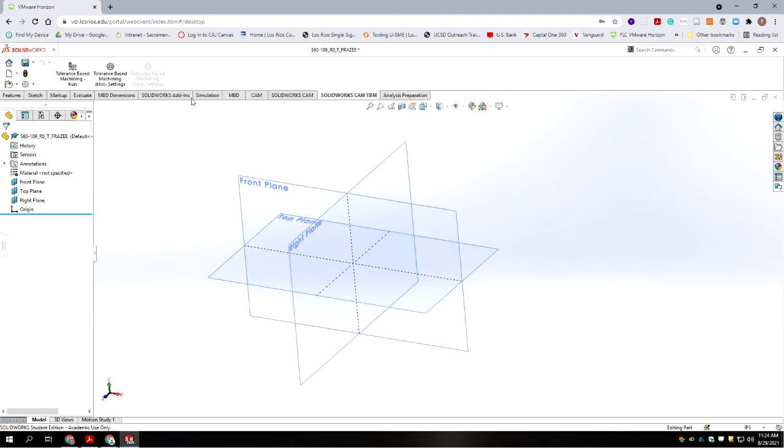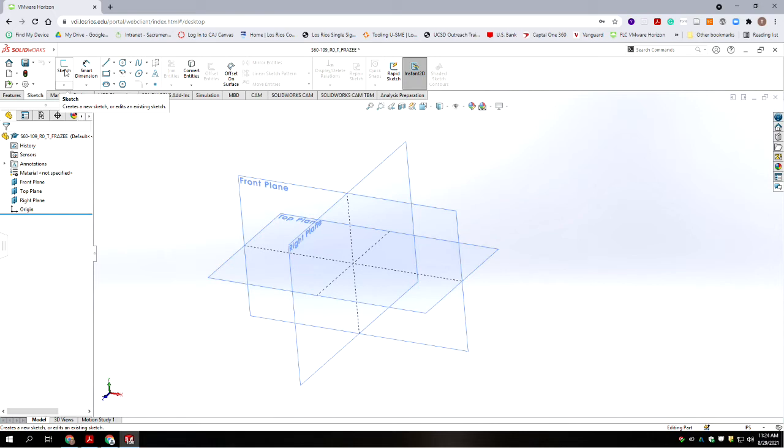So we're going to go through, and first you start off in sketch mode, which is the sketch workspace. Select sketch, and then select the sketch icon, and that enters the workspace itself. It says you're going to create a sketch, and there are going to be things contained within that sketch, like an envelope. Now, for more advanced geometry, you have to have multiple sketches.